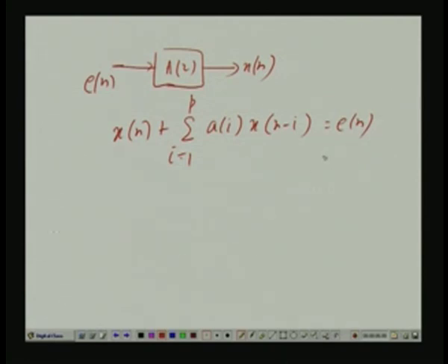If it is an AR modeling problem, En is a white sequence and is orthogonal to all the past of x. Okay. In the case of linear prediction, En is not a white sequence. En is orthogonal only to xn minus 1 up to xn minus p. In general, it is not an orthogonal sequence. In any case, En will be a sequence. So, you can model this even in the case of linear prediction. You can model this by a filter like this: there is a linear prediction error sequence called En, which may not be white, and is white in the case of an AR process.